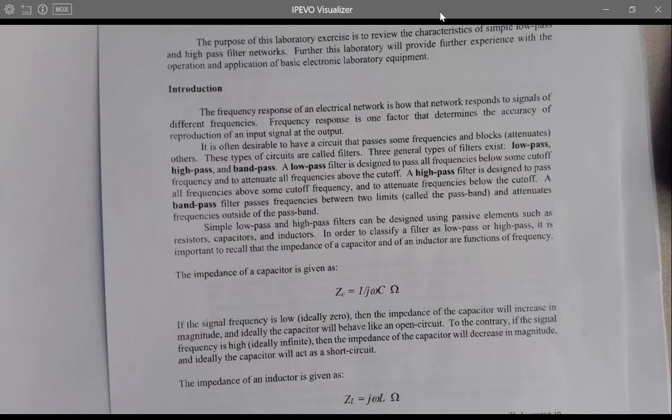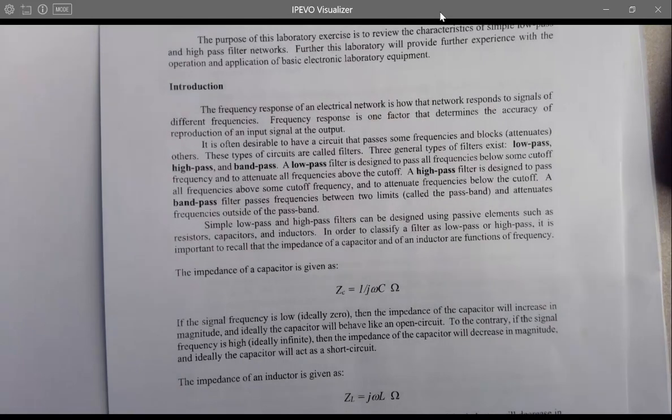Exactly. So when you are applying that DC coupling on your oscilloscope, if you press DC coupling, are you getting all the signals, or only the DC signal or the AC signal? Remember when you added a DC offset in the op-amp lab you did, right? Sometimes you choose DC coupling, sometimes you choose AC coupling.